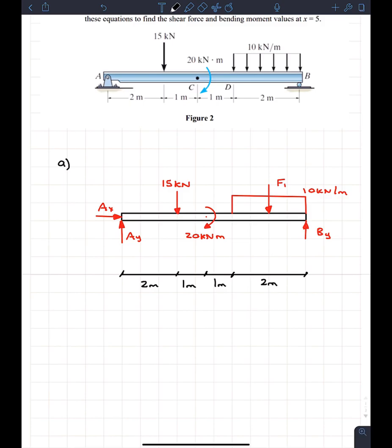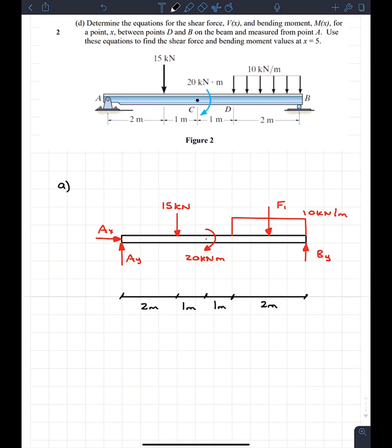So now this is one of the things I get asked. So for this free body diagram, it's good to go. It has all my external forces. It has all my reaction forces, and to finish it off, it has the dimensions of the beam. Now, one thing I got asked about a lot is this right here, this vertical force for F1. And I include this when I'm solving for support reactions. So the question I got asked is, when do I turn the distributed load into a single force?